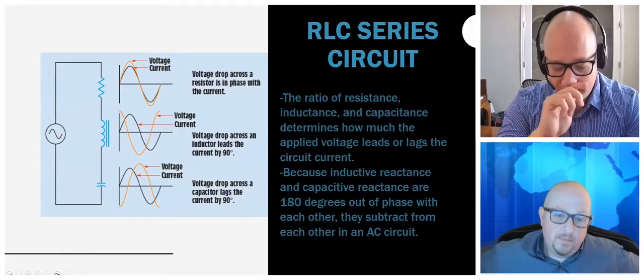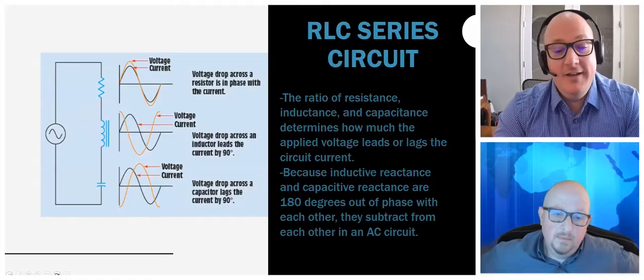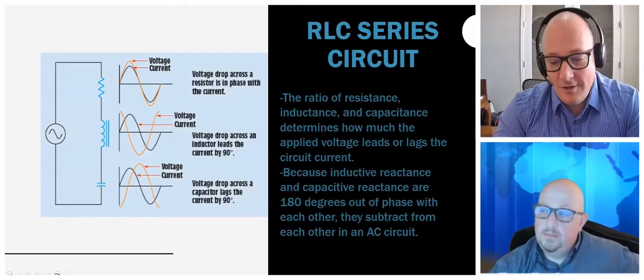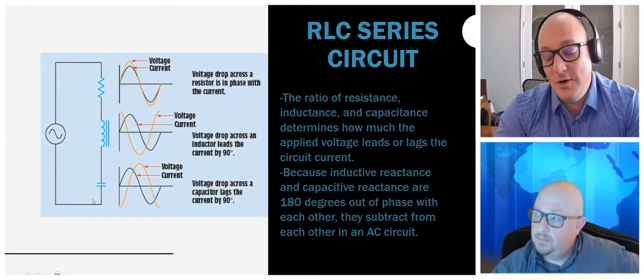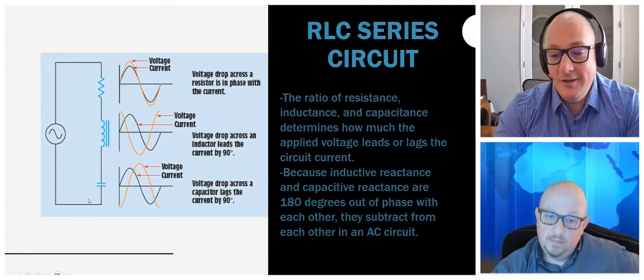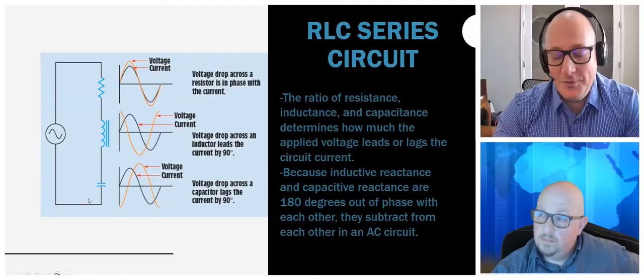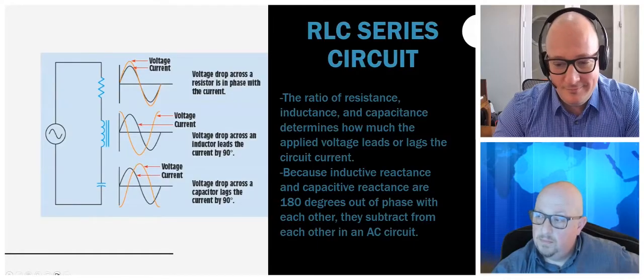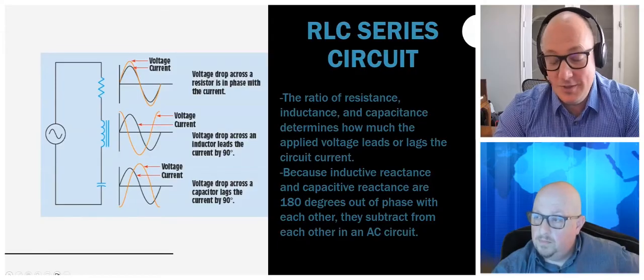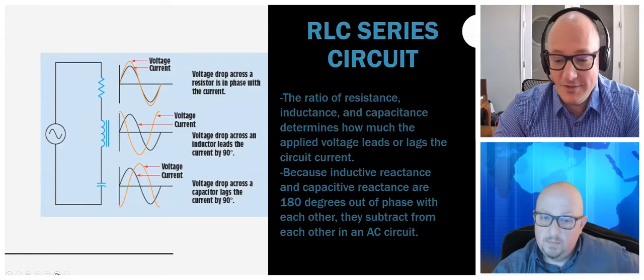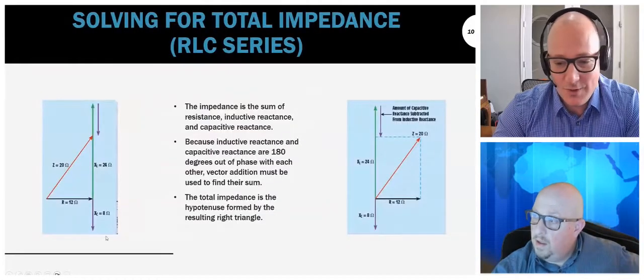That said, columns and rows, the total is always the hypotenuse, and a row has to be solved vectorially. They're in different directions. Well, I just referred to one being the hypotenuse, right? What's the furthest we can get voltage and current out of phase with each other? 90 degrees. So it's as simple as a squared plus b squared equals c squared.